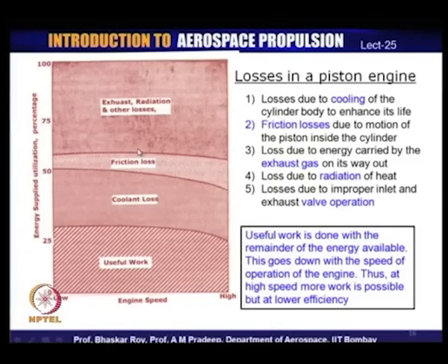And the other important loss is due to the heat that is produced within the cylinder going out with the exhaust gas, which takes away a lot of heat with it. So, the exhaust gas, when it is forced out of the cylinder, goes away with a lot of heat. That loss of heat, the radiation losses and many other such heat related losses put together amount to a large amount of losses.